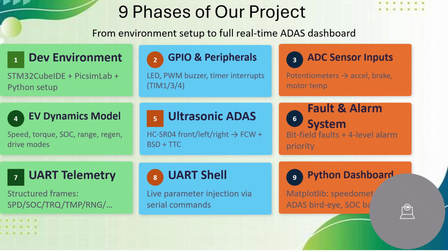When we go to our seventh phase, we have found UART telemetry. UART stands for universal asynchronous receiver and transmitter. In this we have created the structure frame of SPD, SOC, TRQ, TMP, RNG and such things.